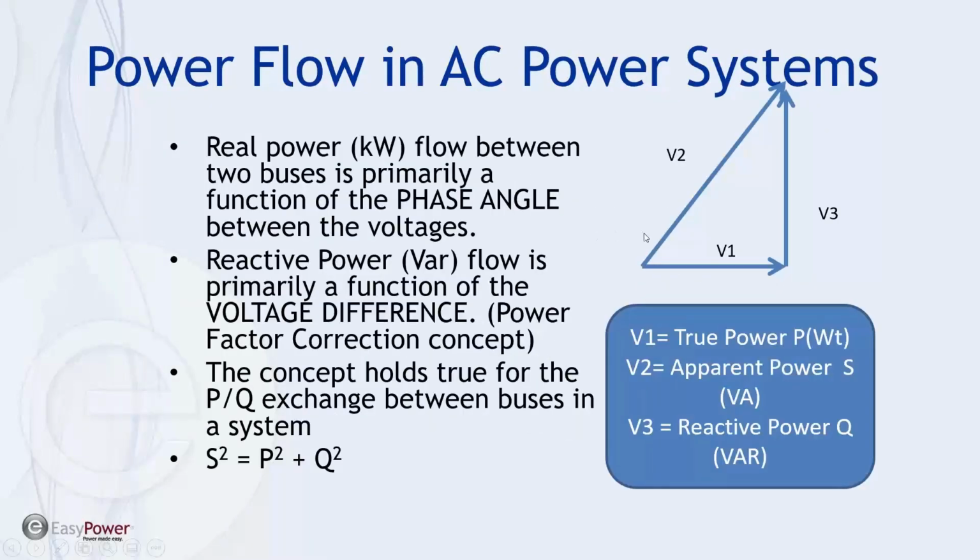Now, this is always something that's a little bit difficult to envision if you haven't bought into the process. And that is, we're talking about the difference between real power and reactive power. The real power is what we use to do work, and the reactive power is what it takes to overcome the reactive impedance of the system.